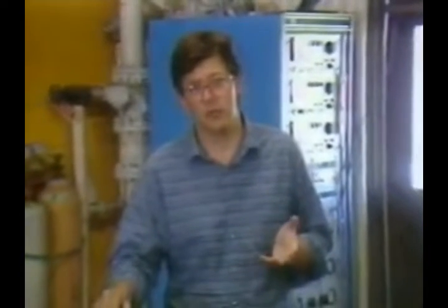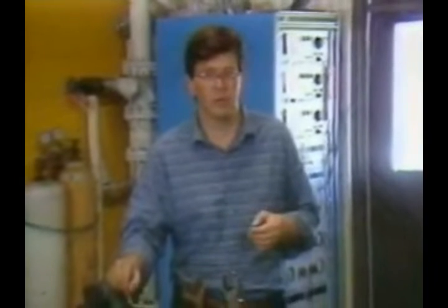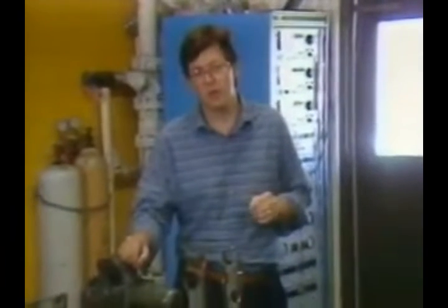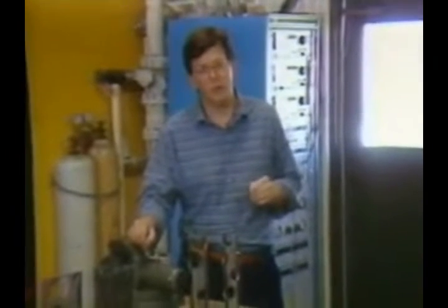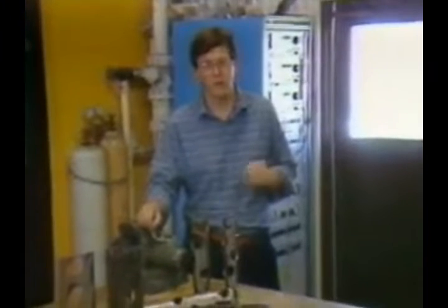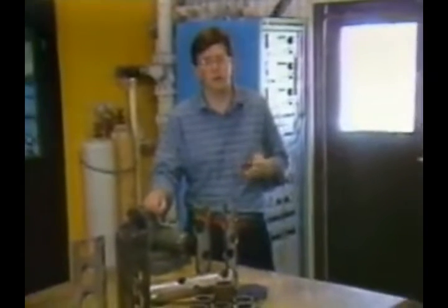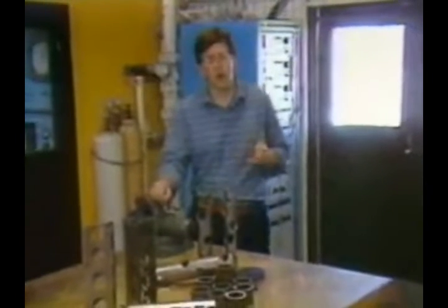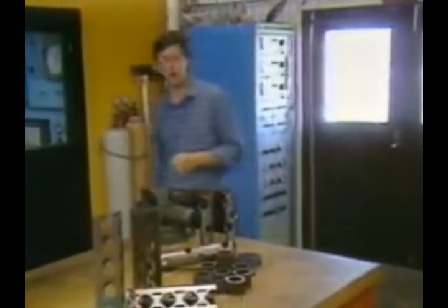If we suspect serious drilling damage, we may decide to use expendable charges for maximum penetration and accept the risk of gun breakage, extra debris, and possible casing damage. However, if the well is deep and hot, the durability of a hollow carrier may be important enough to bargain some loss of penetration for a higher percentage of properly fired charges.